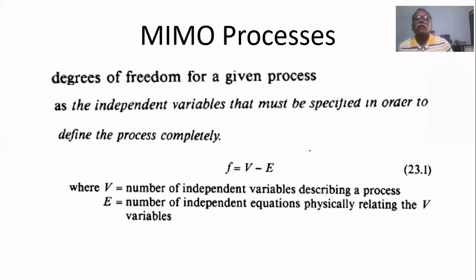It's not possible. In the same way, suppose in a process we can control only 4 variables. In that process, suppose you try to control, you designed 5 loops to control 5 variables. Means any 2 will be in contradiction among those variables. That's why it is very, very important to find how many process variables can be controlled in a MIMO process. First of all, we must know what is a MIMO process. Many inputs, many outputs process.